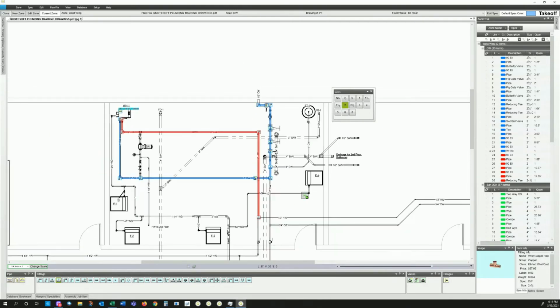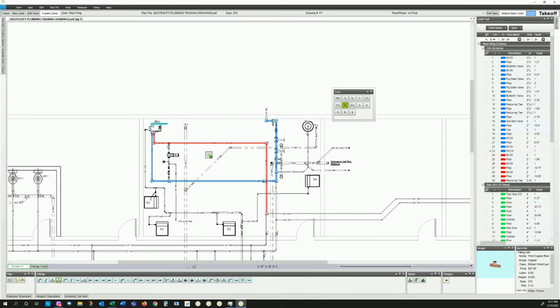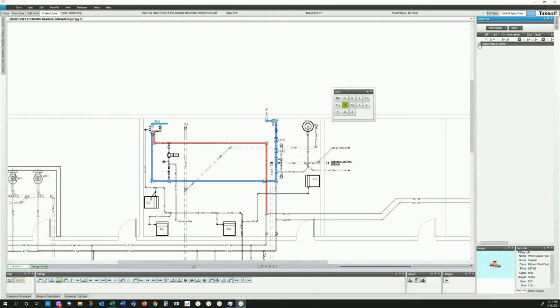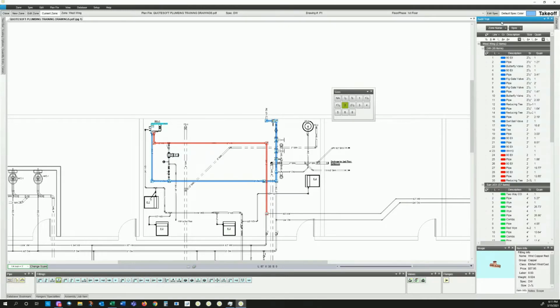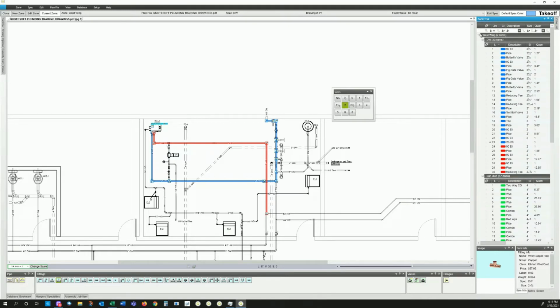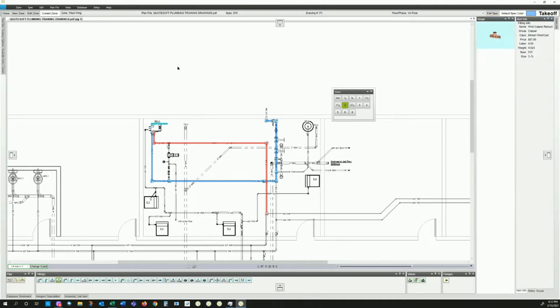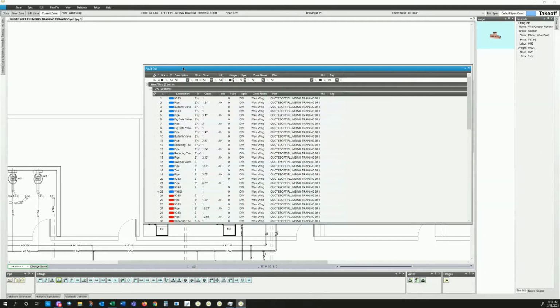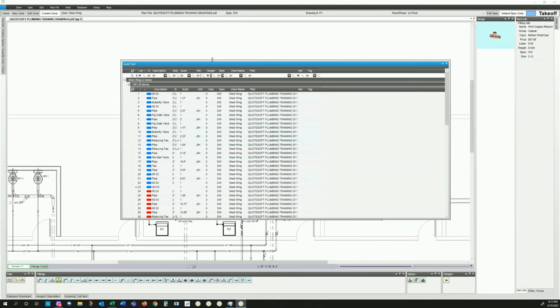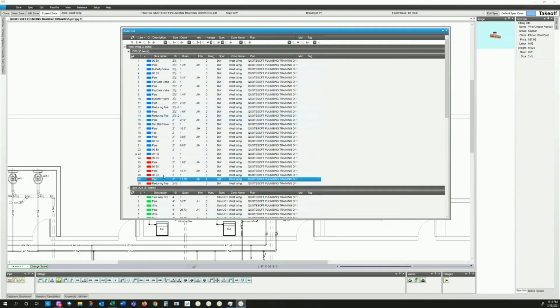All right, we won't do this in full takeoff, but I do like to show you that we separate these colors here, and we actually have these colors separate on the audit trail as well as the previous zone we're working on. So you notice here's our entire west wing takeoff. I've got this audit trail here sorted by zone and spec, and so you see my domestic water here and my sanitary. And what's helpful about this is if I drag this audit trail out here, where we can make better use of it, I can easily sort and filter by any of these categories.